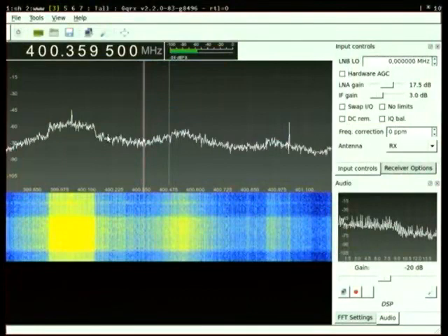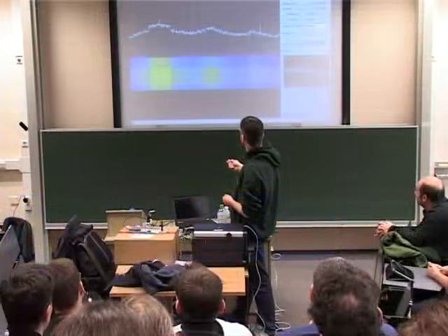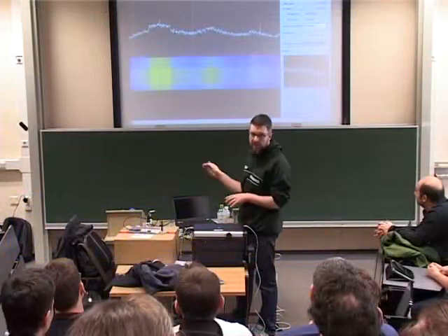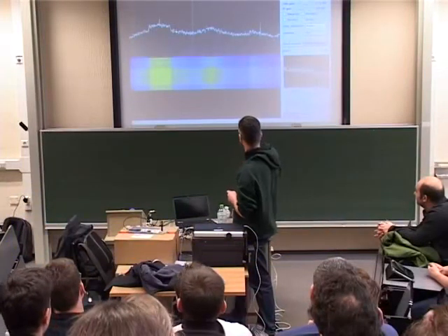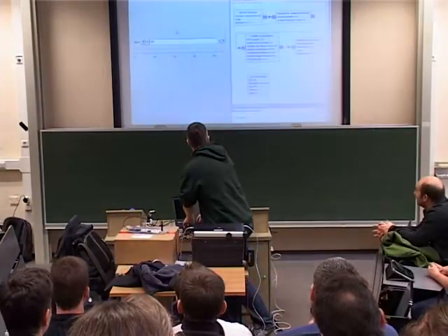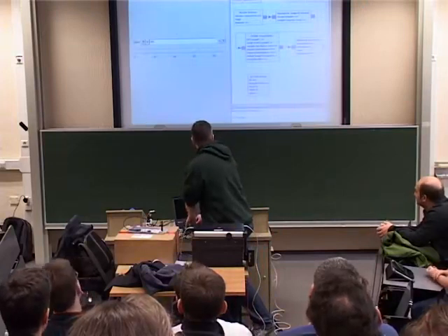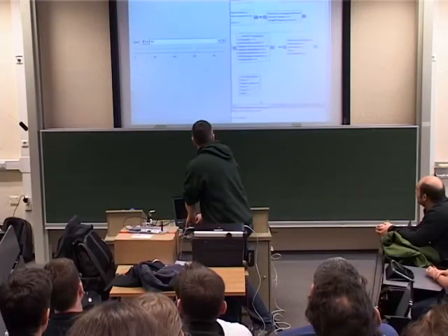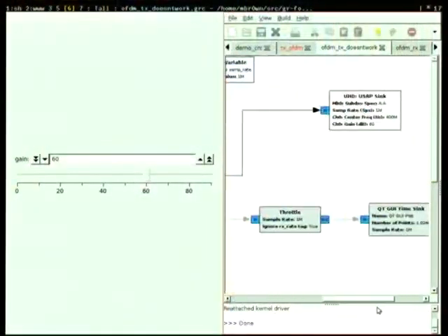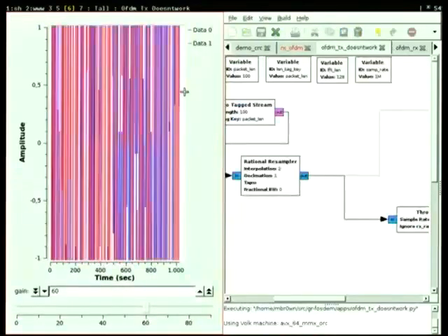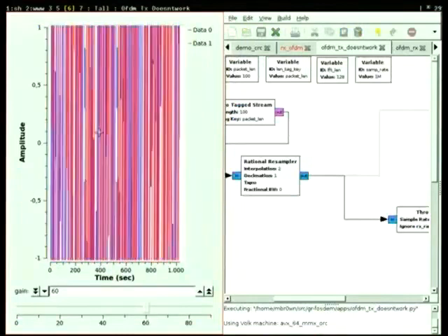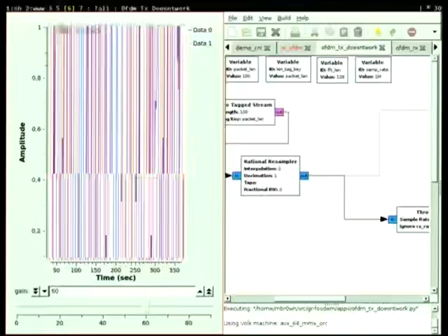I'm just going to tell you what the answer is. This is kind of going the right way, but if I'd started the transmitter after the receiver, you would have seen a huge increase of noise floor here. And what I did wrong was, well, I did it right because I wanted to show you what to do wrong. I'm piping the output of this straight into the USRP sink, and the reason this is a problem is, I'm just going to restart the transmitter.